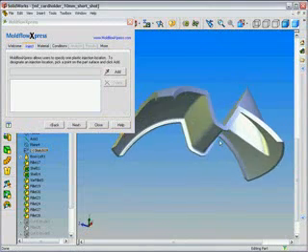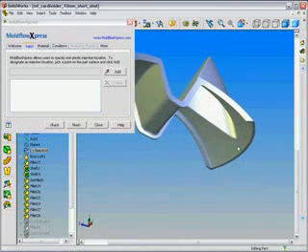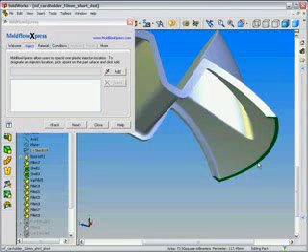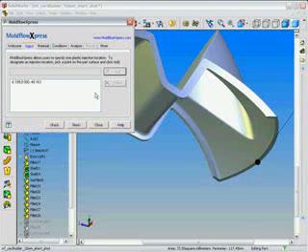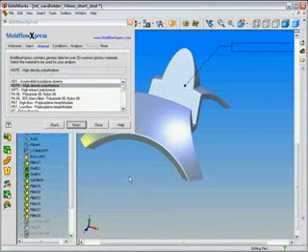Users are allowed to specify a single injection point where the material will fill the part during the injection molding process. To do this, users simply select the face. As they step through the wizard, they're prompted with each step or next phase. Users then choose a material.